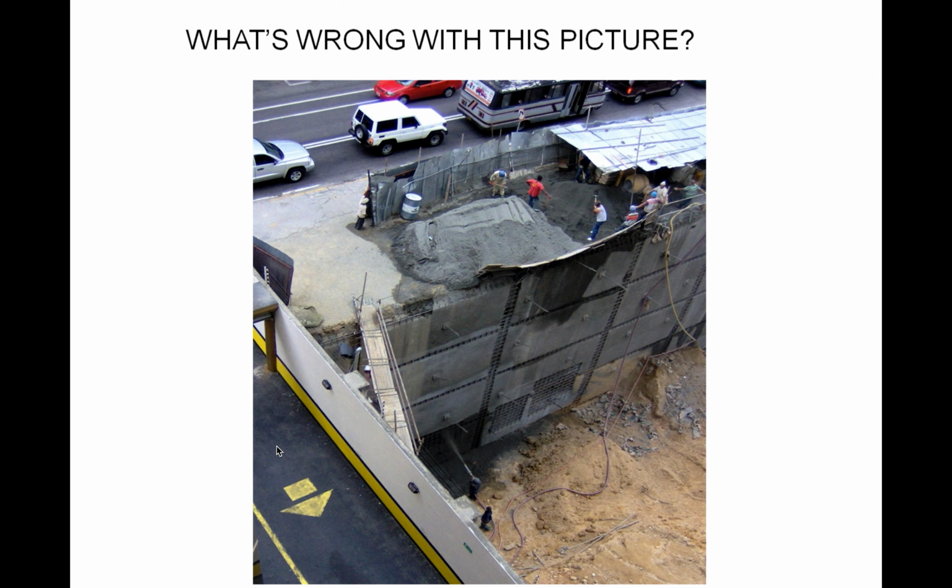All right, so based on some of the things we've talked about over the first few lectures and this lecture, we can see here that we have some issues. They have their materials stockpiled in a location that doesn't have a permanent catchment for it. So what they're using to prevent that stockpile of cement, dry cement mix, is a temporary plywood platform that doesn't even seem to have any real support or backing.